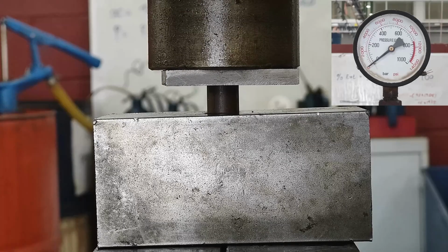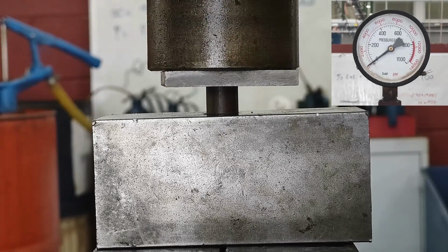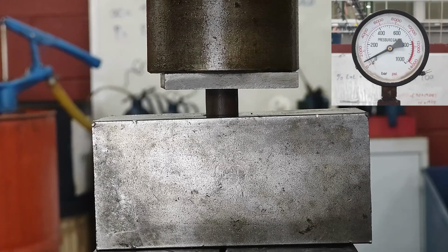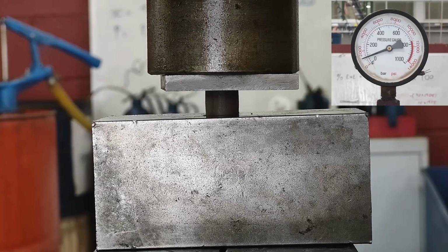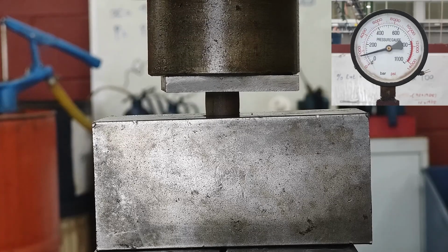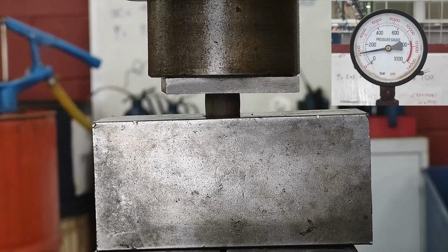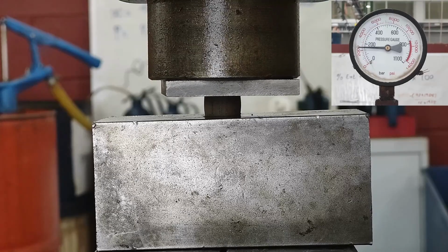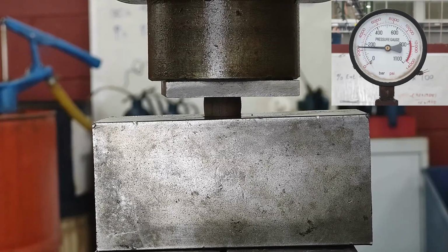The brass sample undergoes significant plastic deformation, work hardening the material. Eventually the material fails under compression in a sudden and brittle type failure mode at 45 degrees to the normal plane. The brass sample was not able to withstand as high compressive loads as the mild steel or the cast iron.